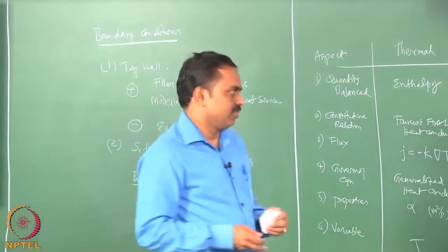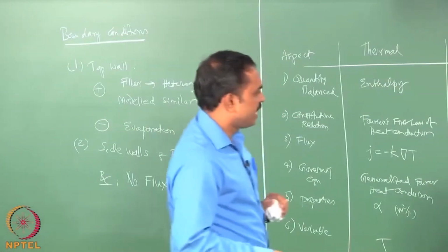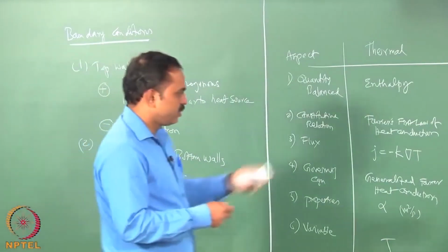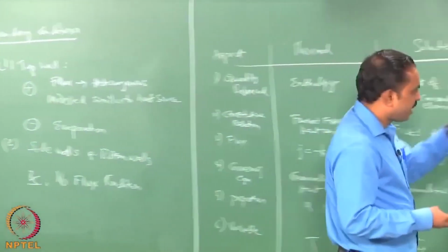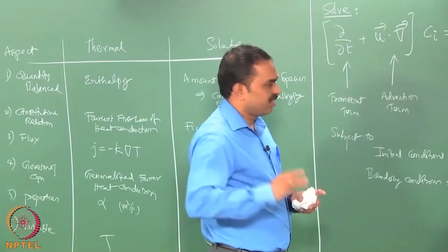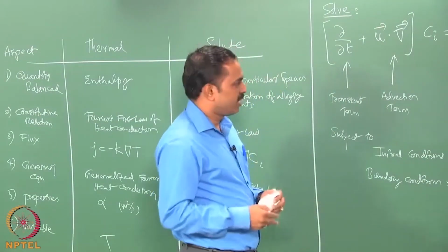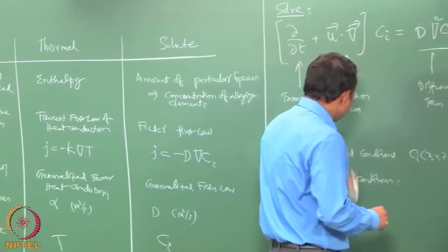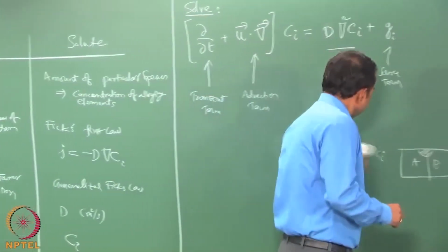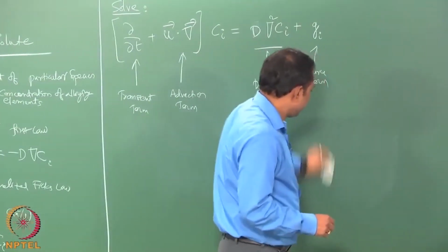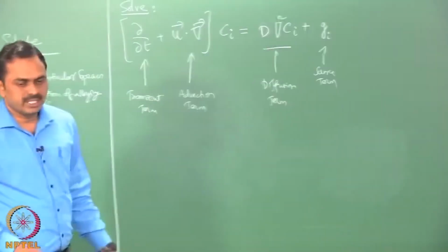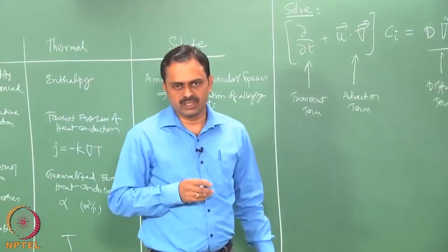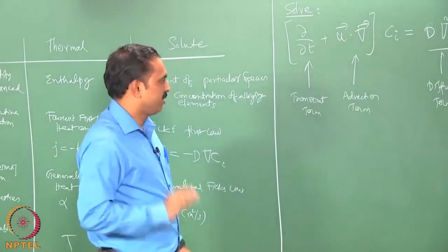And one word about the special terms. Okay, so, we have this source term that is there. Do we need to have any special term is a question, and I would just suggest that we can have it, and it will be clear when the module on the micro scale modeling is completed. Let us just look at that briefly, if there is any need for a special term. In the case of the heat transfer or thermal modeling, we had a special term which is basically the enthalpy model to take into account latent heat evolution. So, analogously here also we will have that requirement.